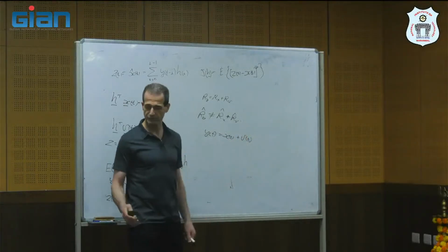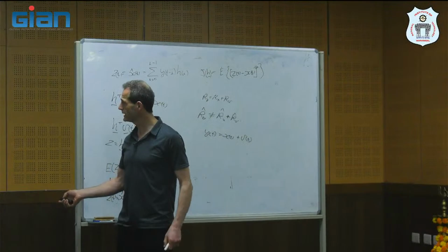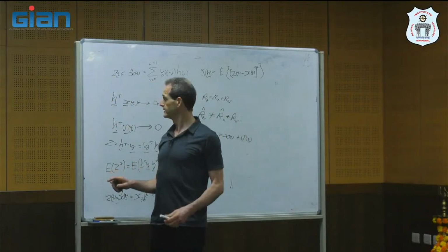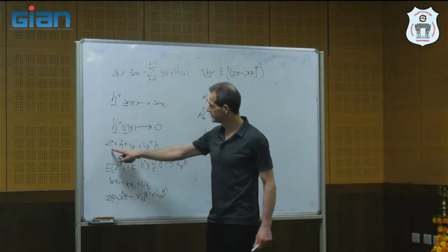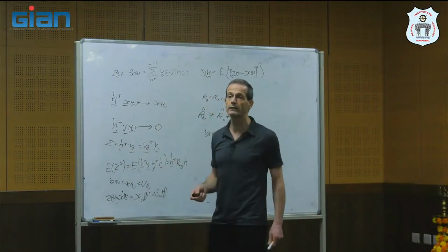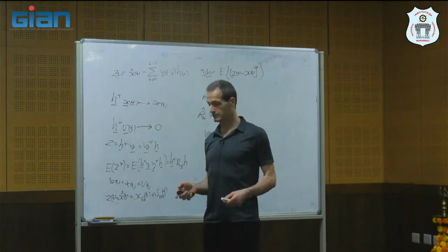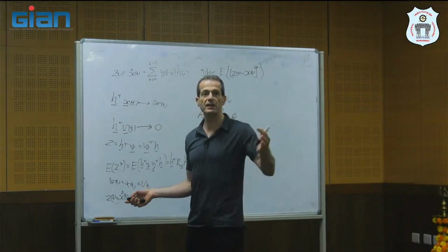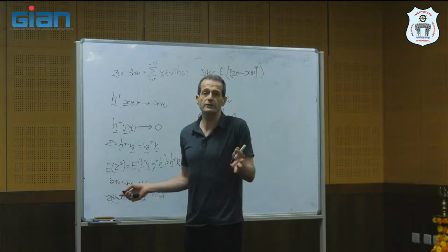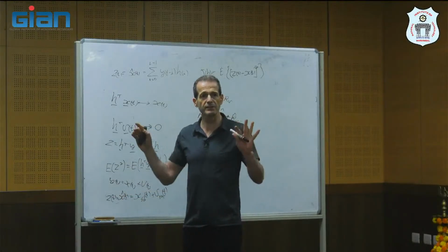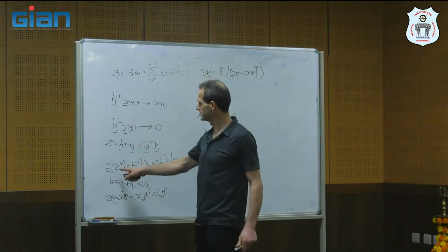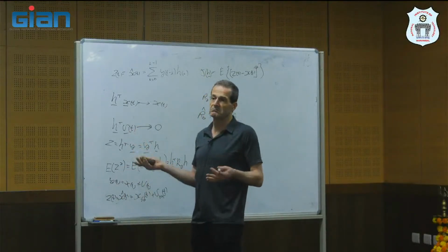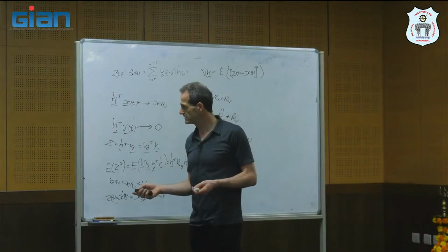And then the Wiener filter goes to the identity, 1 and all zeros. It means that the estimate, Z, will be equal to Y. Makes sense. Because if the input SNR is very high, you don't need to do anything. It's better to keep the signal Z equal to Y, because Y doesn't contain much noise.